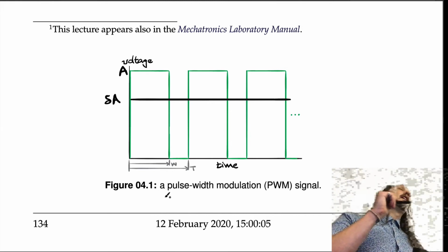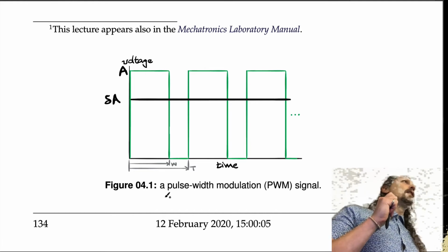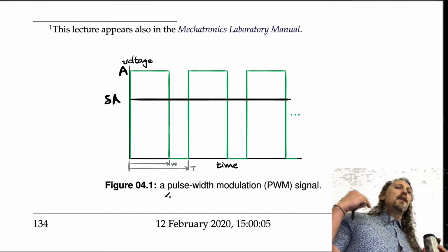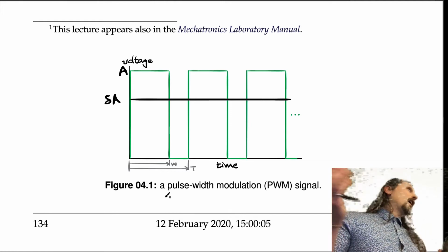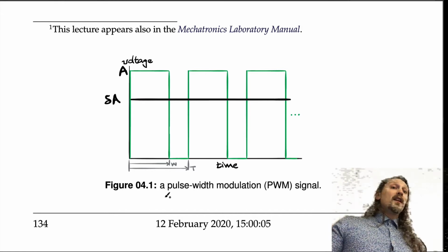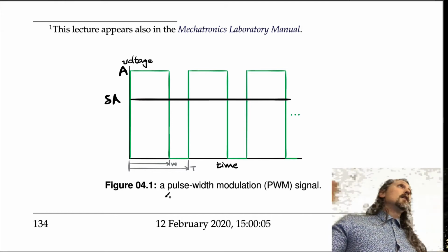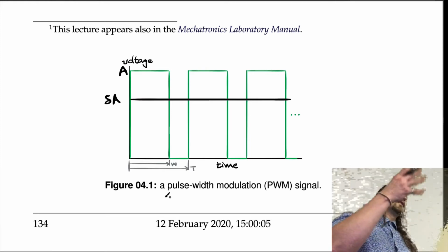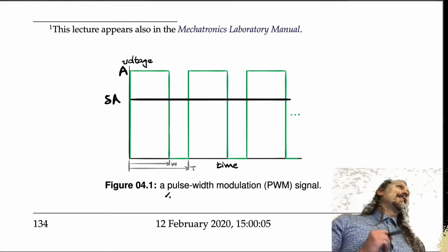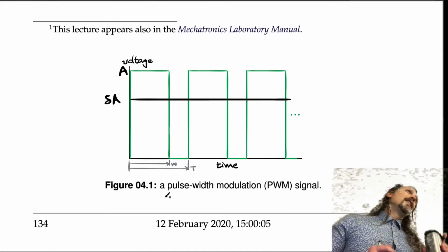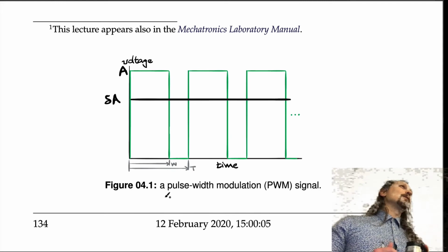So we'll get into a little bit of the details of how we do this, but suffice it to say that we can put these signals in, and if you apply these voltages to a motor, as is very common to do, you get essentially continuous operation, and it doesn't appear to be a weird on-off switched driving. Although there's some nuance to that, so we'll talk about that.